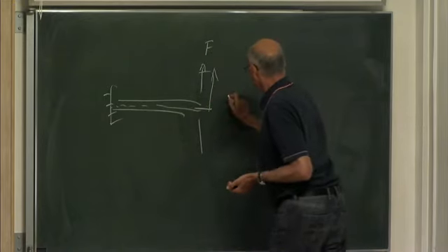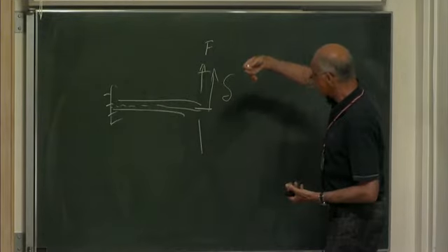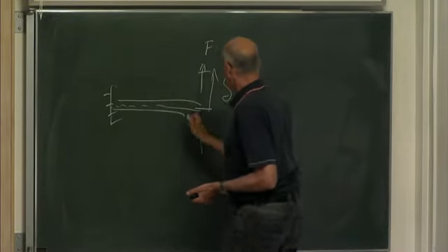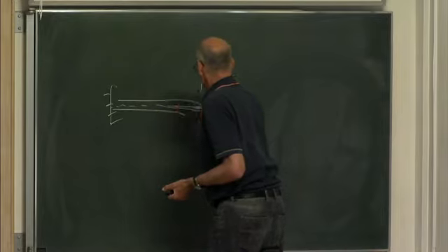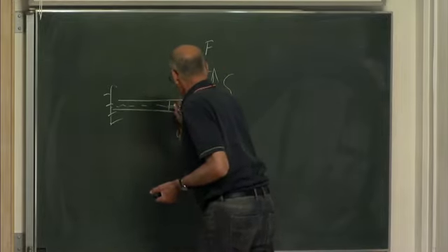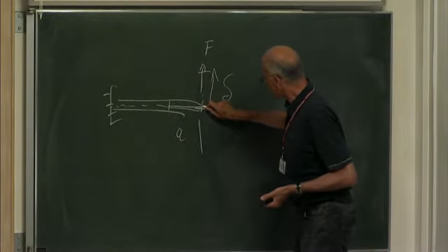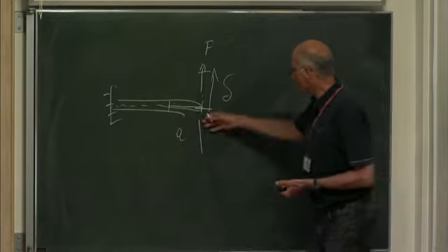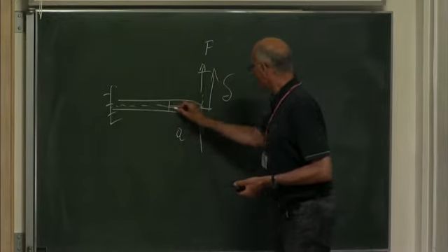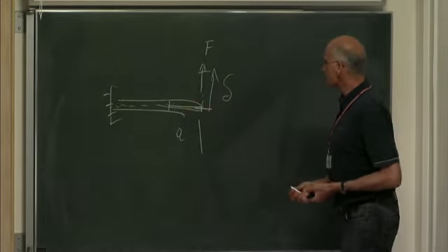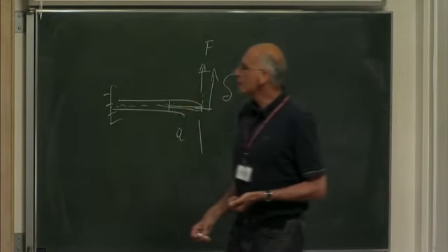You have here the data, the opening of the specimen, and you observe here a crack length. And you measure the displacement here at the free end, but you do not know what's going on here inside the specimen. You do not know the stress field.